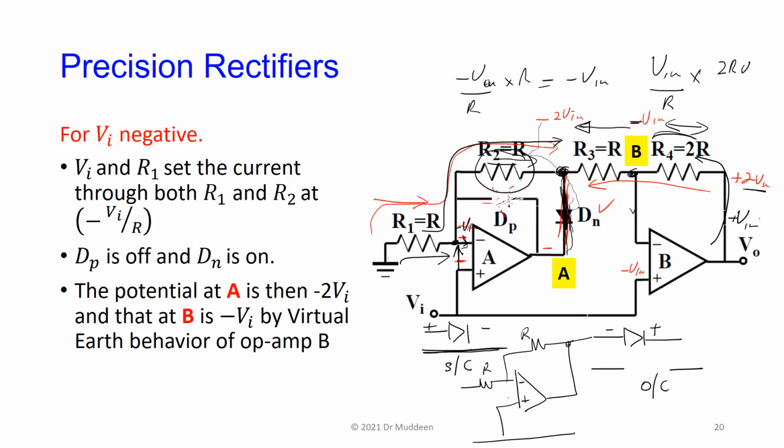As I say, all you really have to do after that is to figure out how an inverting and a non-inverting amplifier works. So you draw the circuit without the diodes in it, and just follow the voltages and the currents.